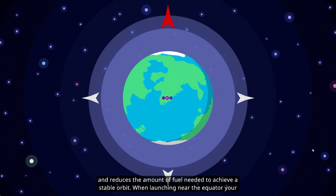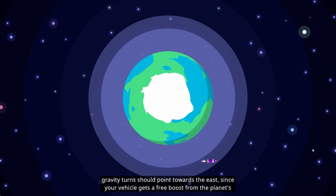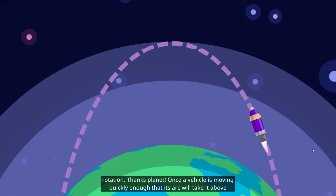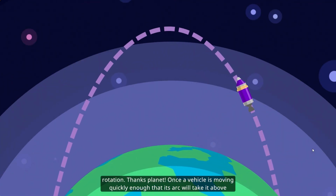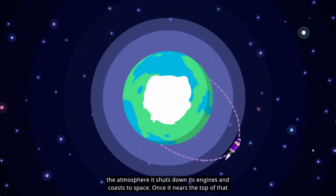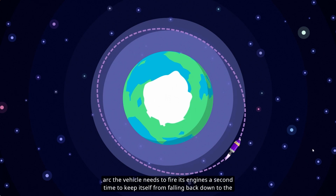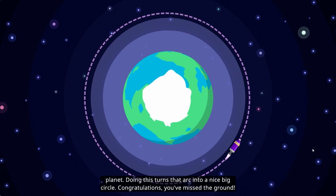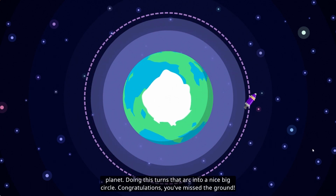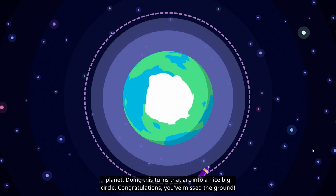When launching near the equator, your gravity turns should point toward the east, since your vehicle gets a free boost from the planet's rotation. Thanks, planet! Once a vehicle is moving quickly enough that its arc will take it above the atmosphere, it shuts down its engines and coasts to space. Once it nears the top of that arc, the vehicle needs to fire its engines a second time to keep itself from falling back down to the planet. Doing this turns that arc into a nice big circle. Congratulations! You've missed the ground.